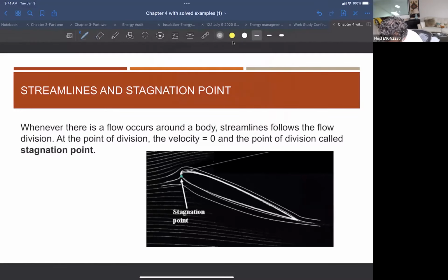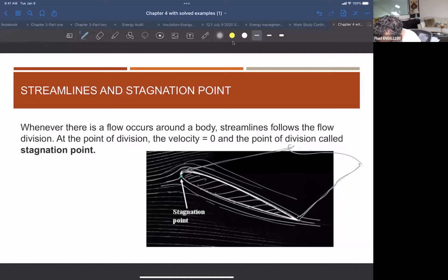Right? So imagine this is your wing. I'm taking just a cross section here. You can look at the fluid streamlines around this aerofoil. By looking at the velocity distribution, the streamlines give you an idea where those lines are coming together, with small distances between them, because you have higher velocity distribution here than on the top one.